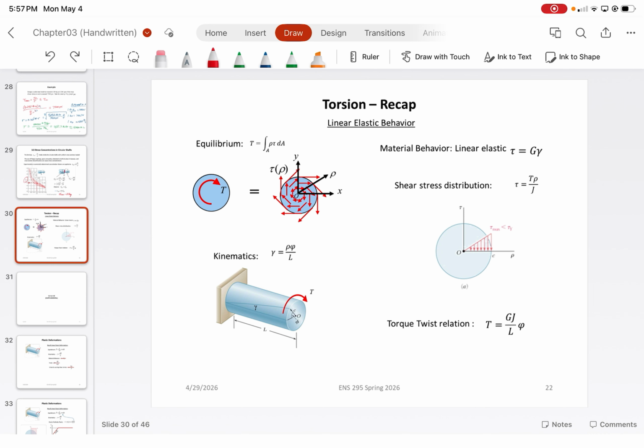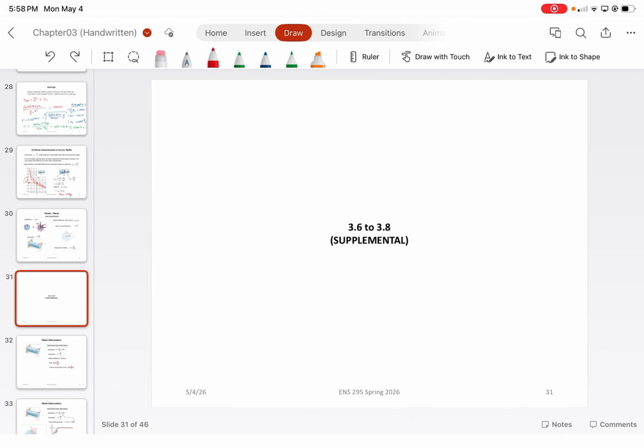And when we do that, we end up with a total torque that's applied to the rod. From there, we can derive equations for how to calculate the angle of twist based on a given torque or vice versa, knowing that the relationship is entirely bounded by Hooke's law. So it's all just relating back to day one of the class: equilibrium, kinematics, compatibility, and Hooke's law.